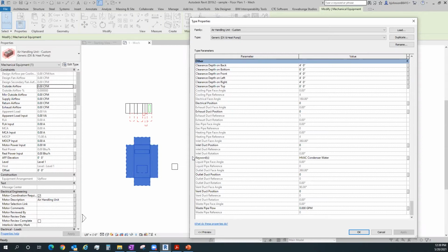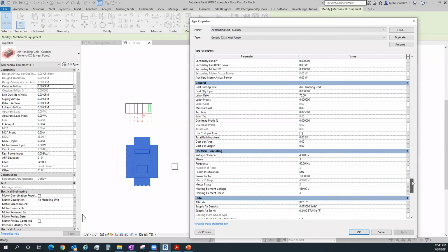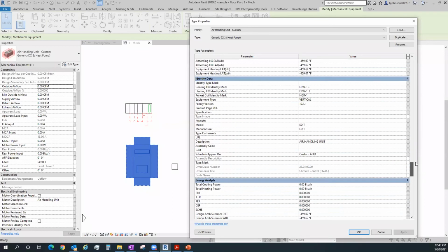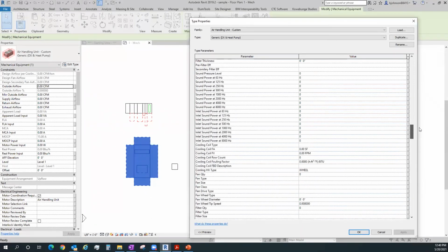And then I would also have dimensions on that duct position that I could move that connector and extrusion around on that face with dimensions as well. So I'd have full control dimensionally and on face of every object that I've placed as an extrusion in that family. So again, with placeholder families and family builds, you can get as bare bones like my cube as you want, or you can get as serious as you want with functionality where you're really programming a tool that can kind of metamorphosize into whatever you want in that case.